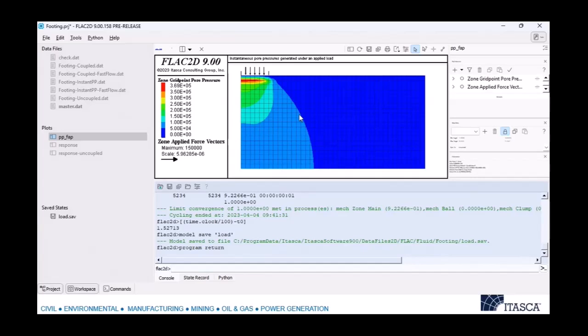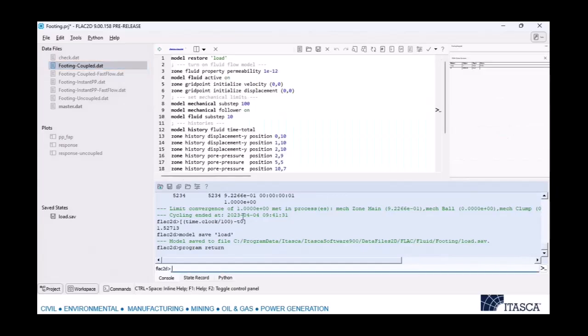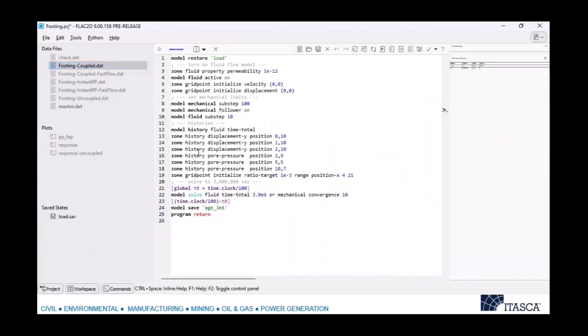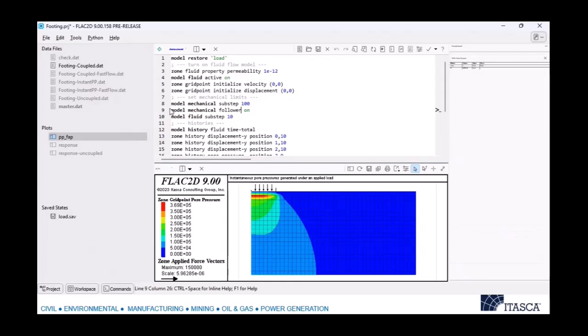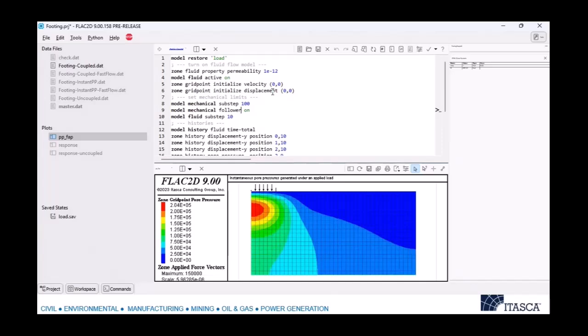We come to equilibrium. And then we say, okay, that happened very quickly. The pore pressure didn't have time to adjust. But then that load stays now. This is like a classic thing. That load stays there. And over time, those pore pressures are going to dissipate. So if we run the next one, you can see that little bulge of pressure starts to drop and spread out.